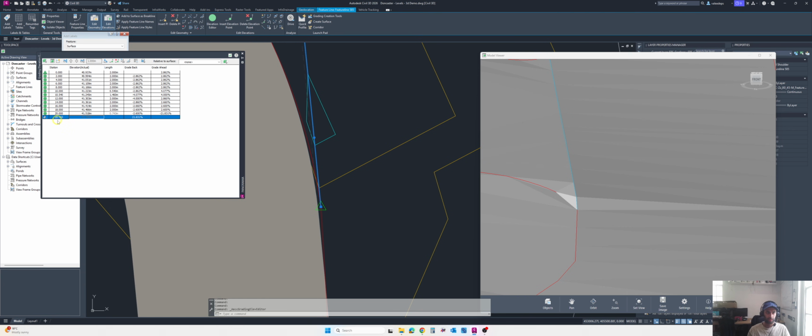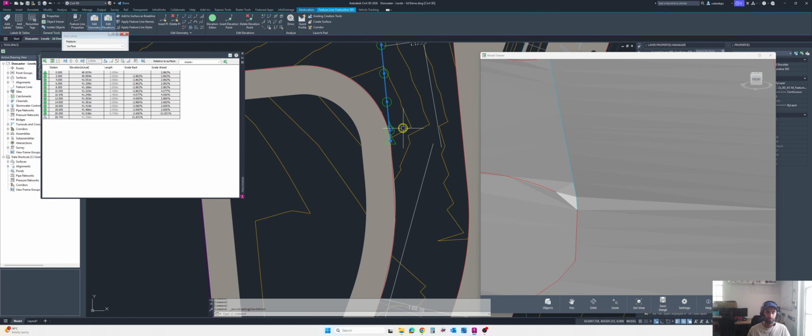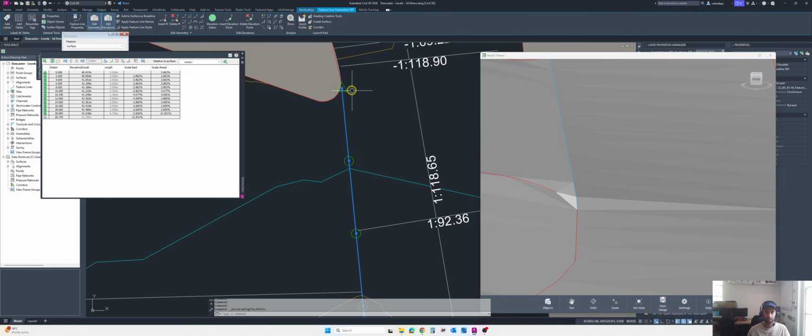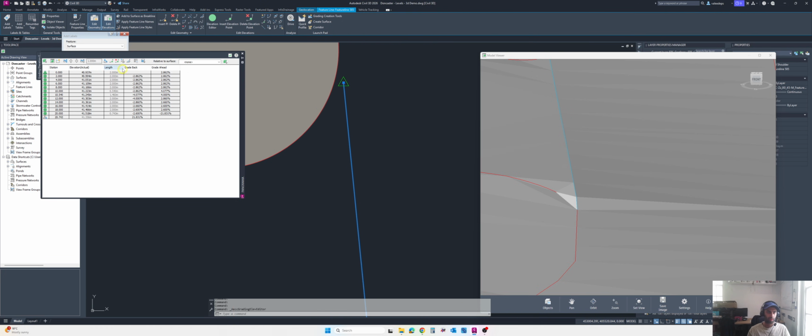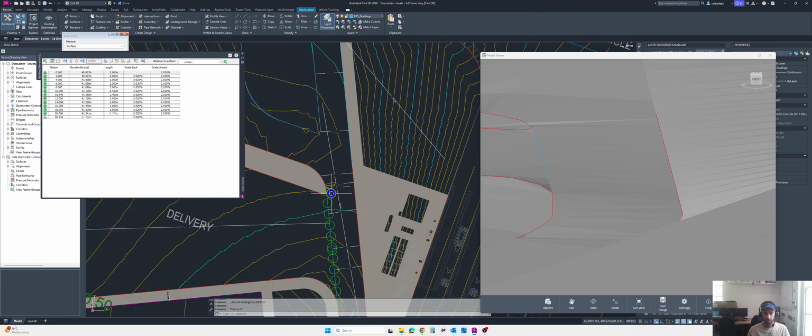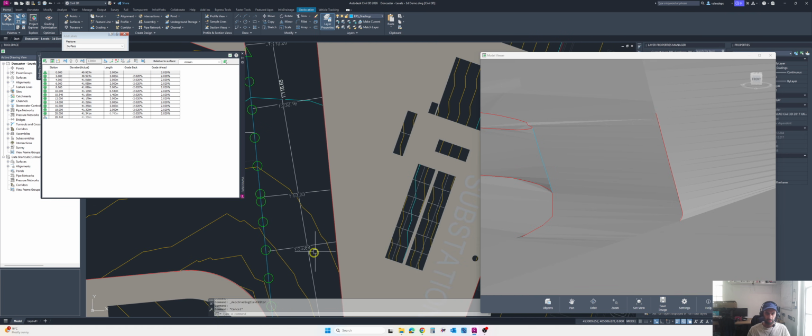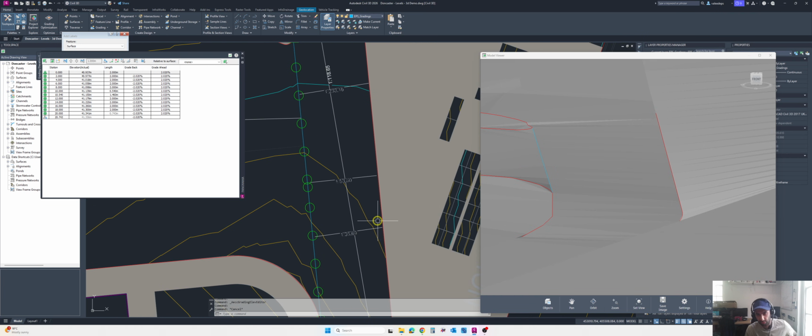So this you can see is grayed out because it depends on the red line, and I can select this one, top to the start. Yeah, this isn't touching, so I can select constant grade. Now it looks nice. Now you can see I have slopes, and this one is 1 in 35. It's fine because it's not like we're designing the whole road network.